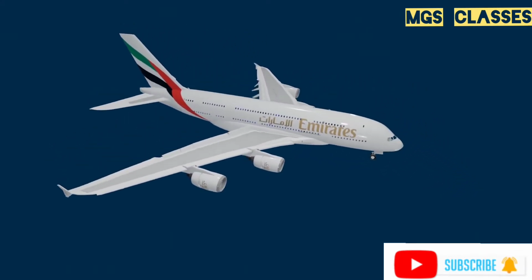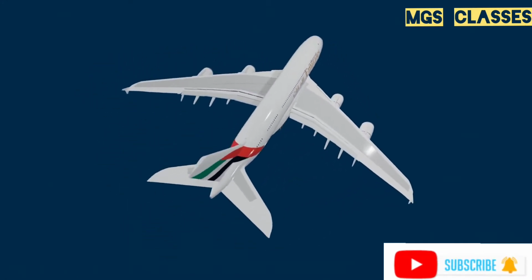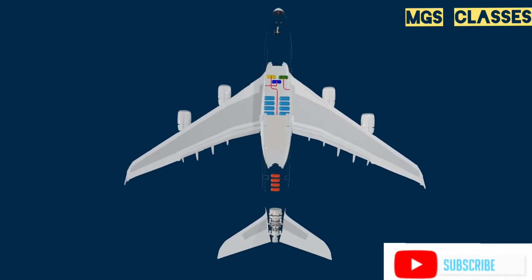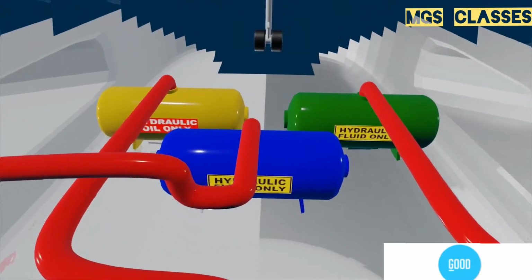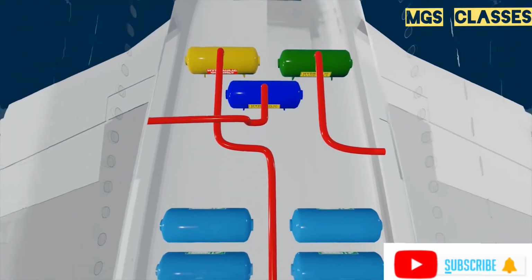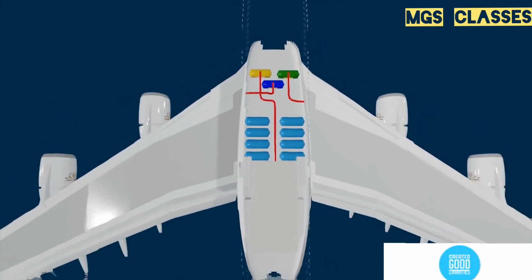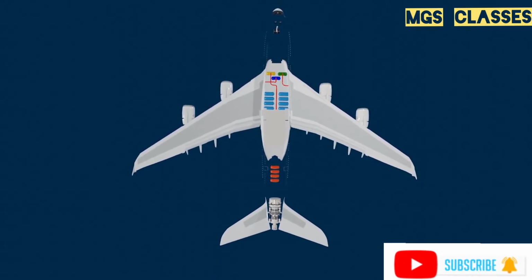The moving parts of the aircraft, such as doors, landing gears, flight controls, etc., are heavier in size and weight, so they need more power to operate. So the hydraulic system is used to operate the heavier parts of the aircraft. There are 3 hydraulic reservoir tanks, green, yellow and blue. The green reservoir is for landing gears, normal brakes, engine 1 reverser, and yaw damper 1. The yellow reservoir tank is used for nose wheel steering, alternate and parking brakes, cargo doors, engine 2 reverser, and yaw damper 2. And the blue tank is used for the emergency generator.